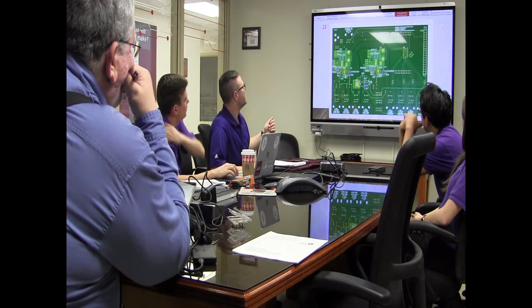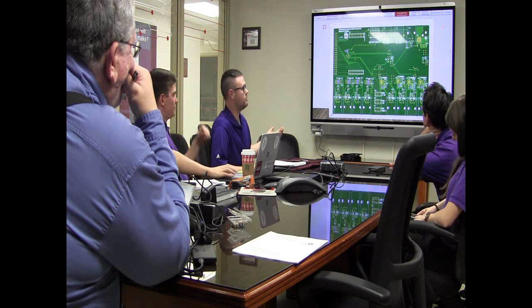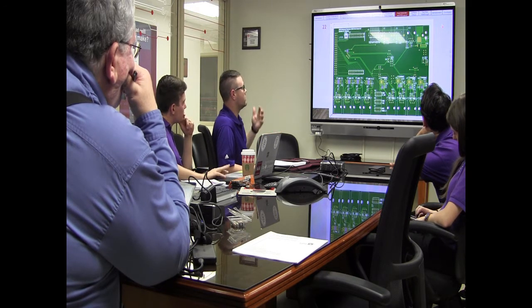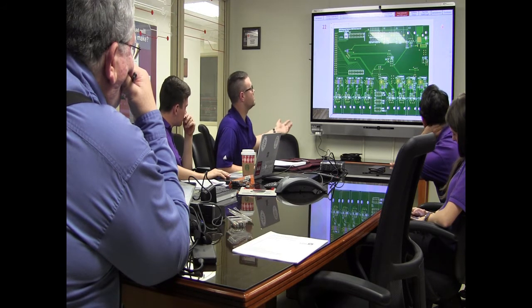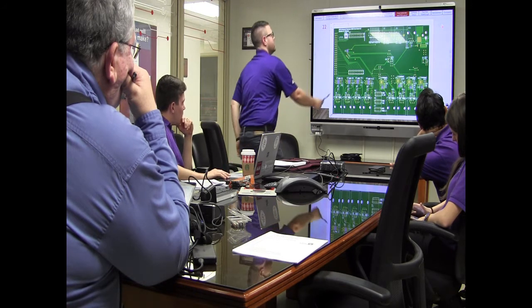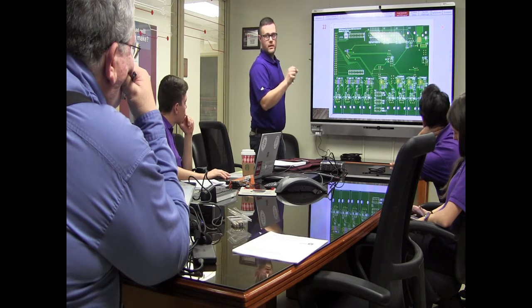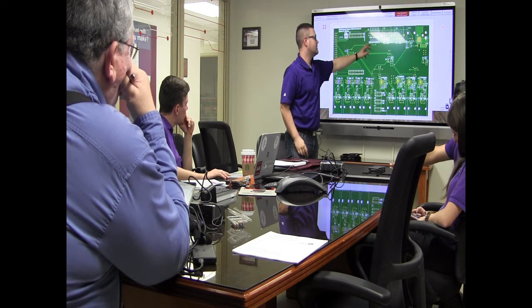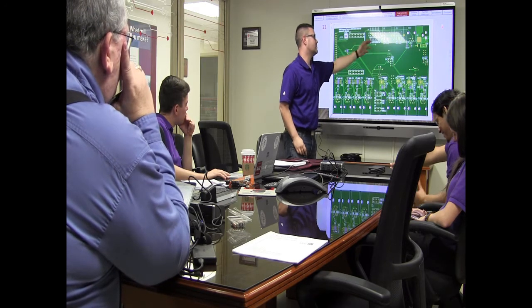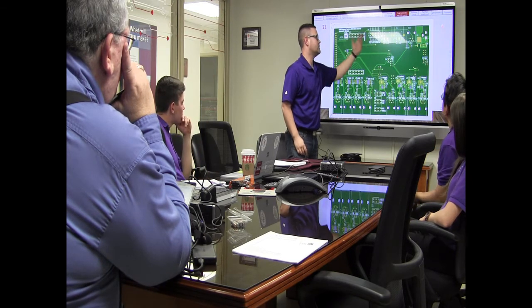Actually, if you go back, something that we implemented in our design from one of the big changes that wasn't hardware related, but just user interface related, was adding a lot to the silk screen. So up over here, this is where you can select the I2C address with little shunt bars. And we even put on here the I2C address select for the PWM driver: all open, your address is 0x40, 1 and 2 are shorted, it's 0x41.